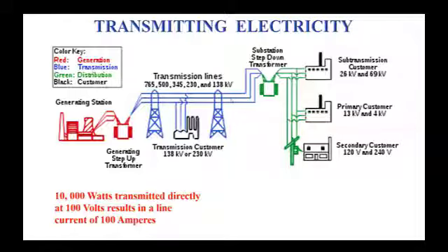But think about the power loss. The power that's created in any type of device is I squared times R. So even if R is very low in these lines, 100 squared, we're talking about a lot of watts, a lot of power that's being wasted as heat in these lines.